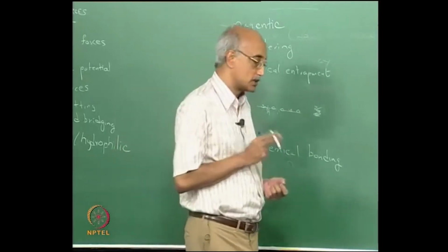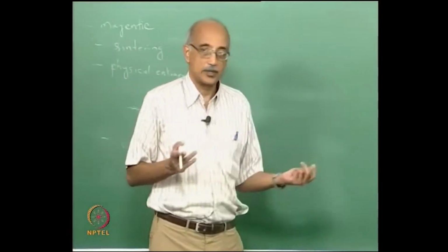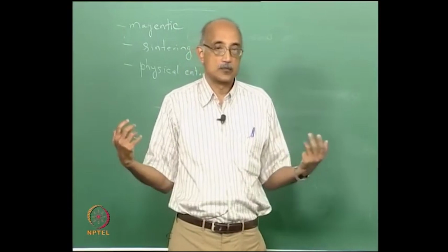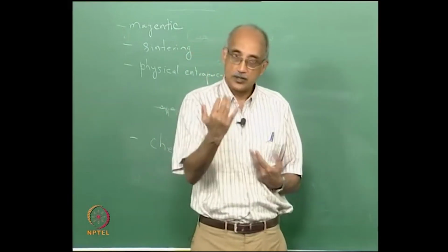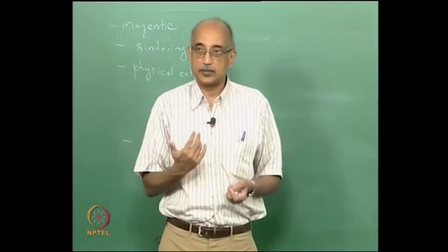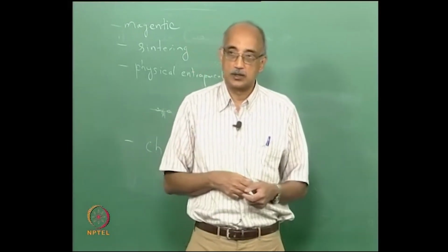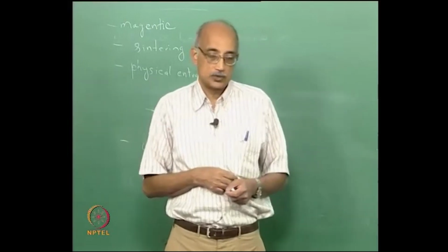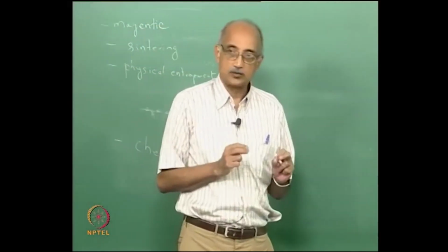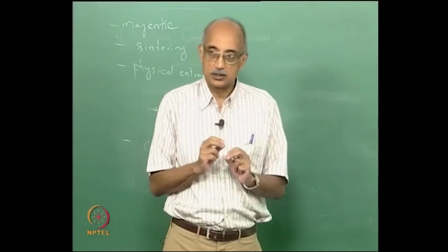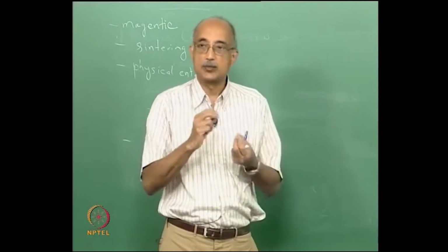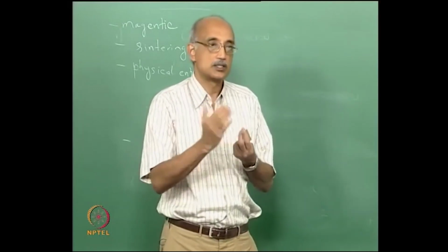Again, van der Waals forces are very fundamental because that's where it all begins. All you have to do is bring any two atoms together or molecules together or particles together, and there will be an immediate atomic level force that is set up between them, and that's called the van der Waals force. Now, what van der Waals force is, it's basically the sum of all the interactions that are set up due to induced dipoles between adjacent atoms.